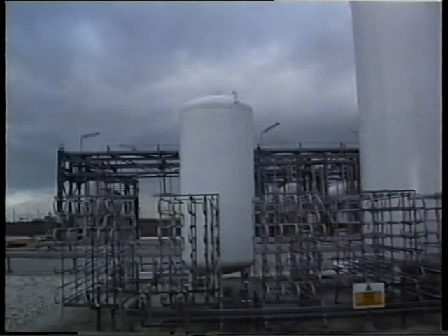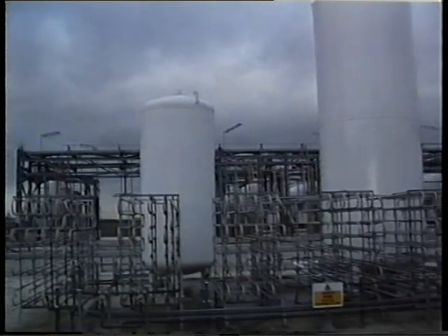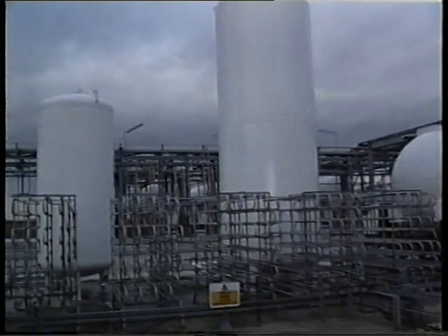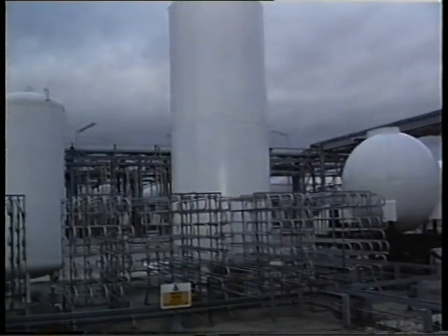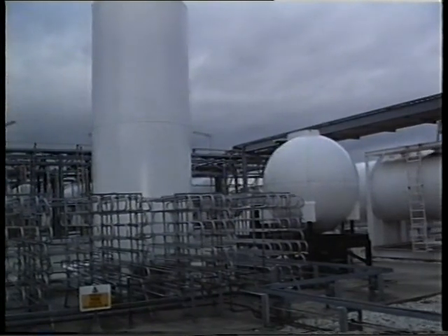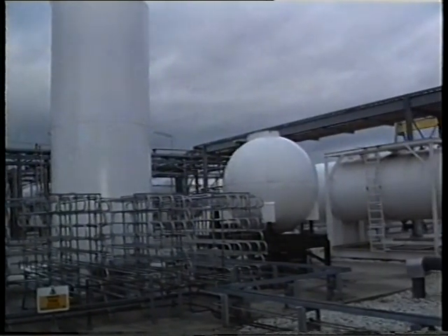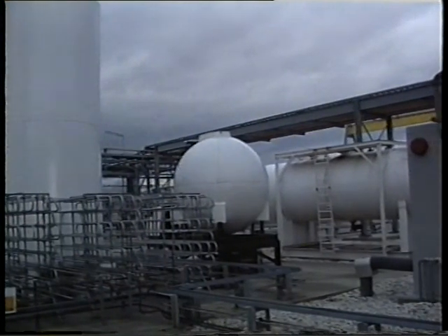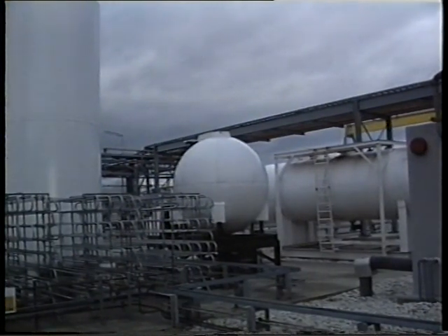Additions of nickel to carbon manganese steel improves toughness at low temperatures for cryogenic uses, and by adding molybdenum and chromium, the creep resistance of the steels improves, allowing use at elevated temperatures. All these steels are resistant to hydrogen cracking and to the detrimental effects of sulfur-bearing hydrocarbons, making them particularly suitable for the petrochemical industry.